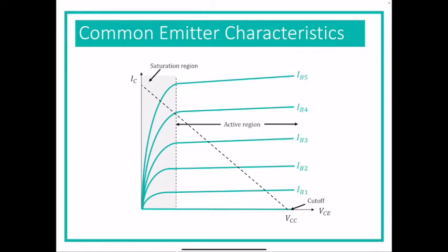So when we look at how a BJT is working, if we want to use it as an amplifier, we're actually going to have to use it in the active region, whereas that was similar to the saturation region in a MOSFET. Where it's operating is called the Q point, and the Q point current and voltage are just related to that particular point at which it's operating.